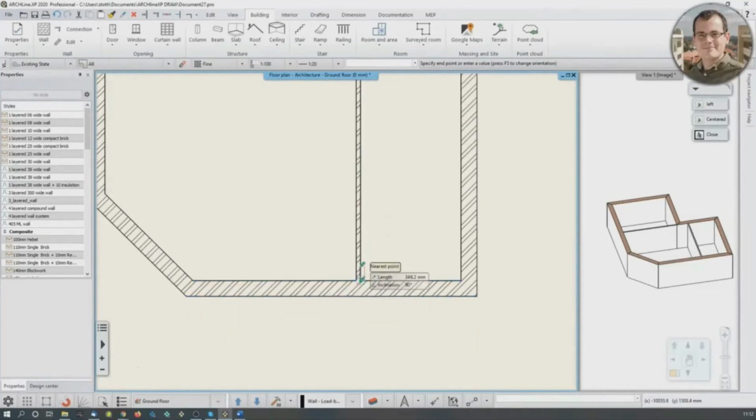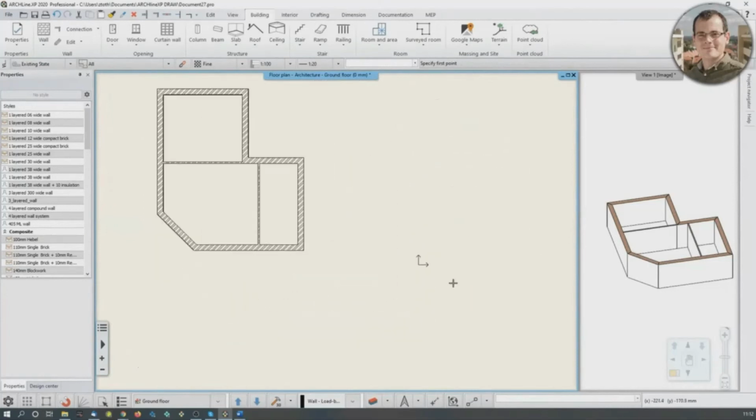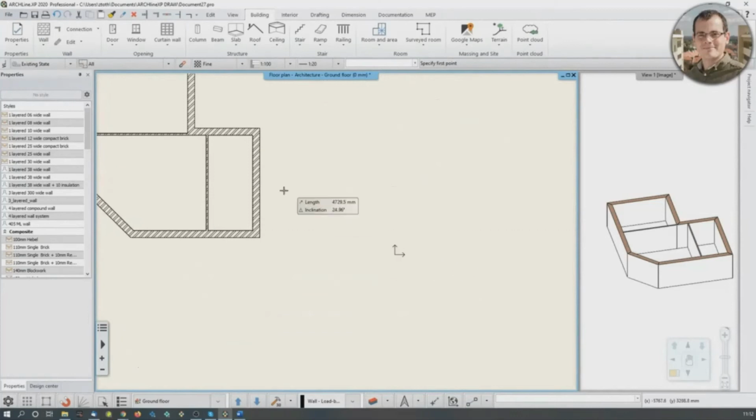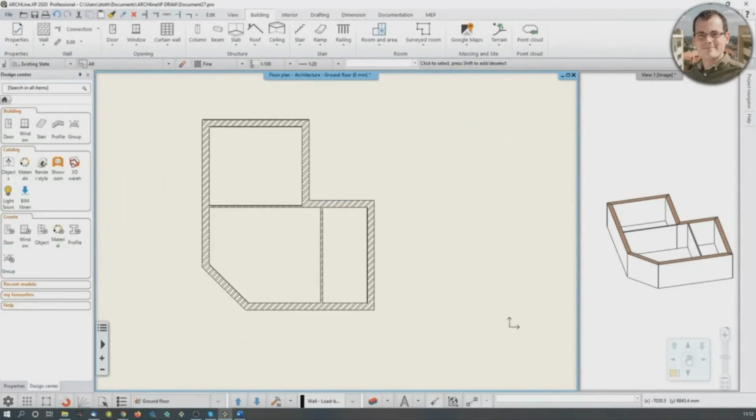So with this very simple tool you can override where your wall is going to be positioned, because if I just hover my mouse, you see that weird values appear, 7,300 and something. Where is this information coming from? It's coming from the project origin. This is where the 0 is, and everything is made in relation to that, because now we are working with sort of global parameters. But if I click on the reference, I can override where this reference is going to be taken from. So that's very important.